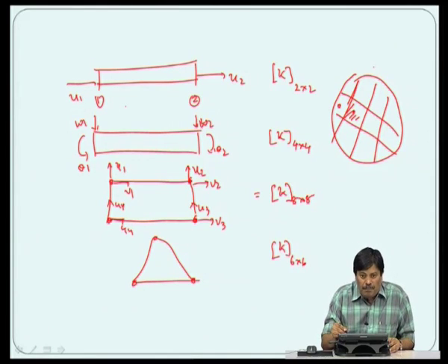However, because of the applied loads somewhere else, there will be forces generated, and the forces across this inter-element boundary will not be compatible, will not be in equilibrium. So, this equilibrium has to be enforced. How do we do that? We generate the matrices here for each of the stiffness matrix. When we assemble it, the assembly process ensures that the forces here are in equilibrium.